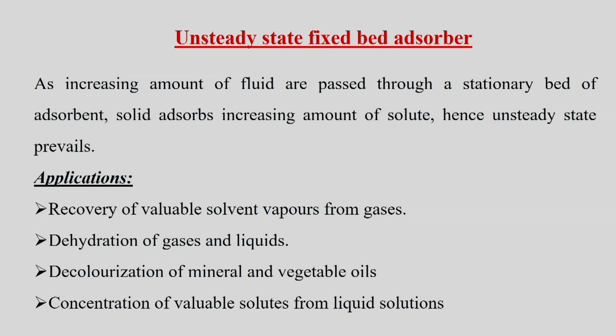In a realistic approach, if a fixed bed adsorber is packed with adsorbent, then layer by layer the adsorbent will adsorb the adsorbate. At any time t, the solute concentration throughout the bed will be non-uniform; it will decrease from the entry point to the exit point of the fixed bed adsorber.